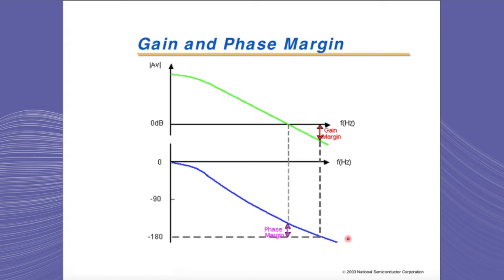In this graphic, we can see the phase margin and the gain margin of an amplifier, which is clearly stable. The gain margin has a negative value, and it is measured when there's been 180 degrees phase shift in the amplifier. The phase margin happens at 0 dB, and the phase lag is less than 180 degrees.